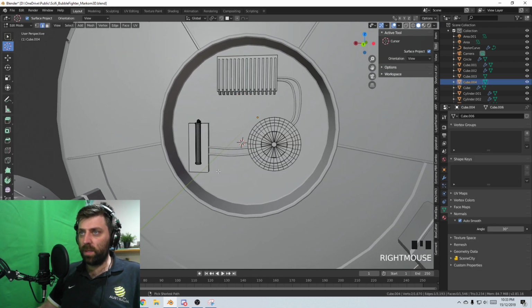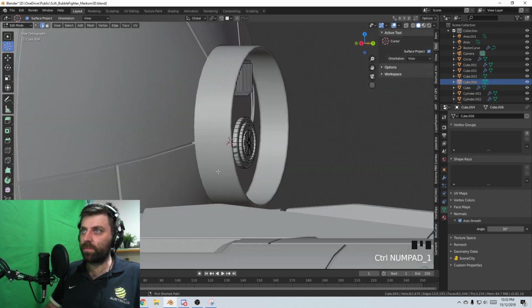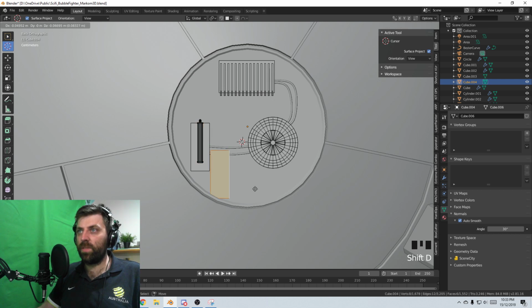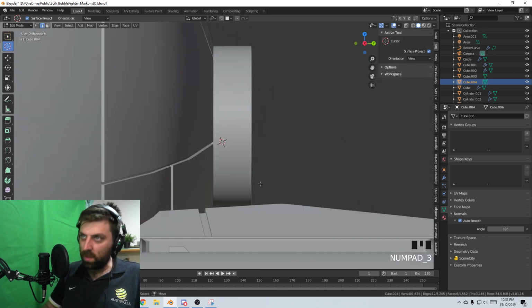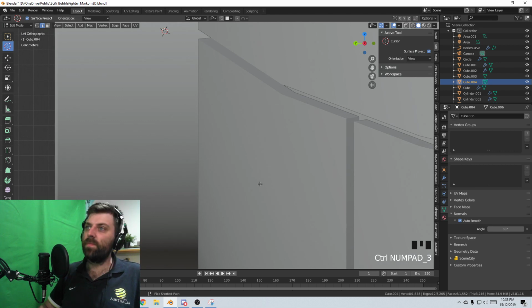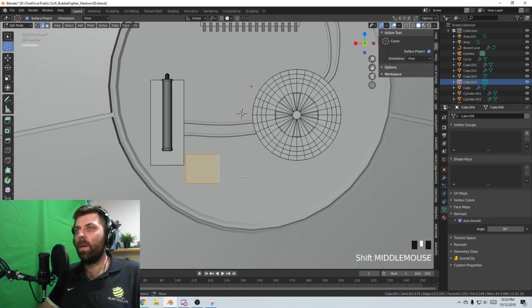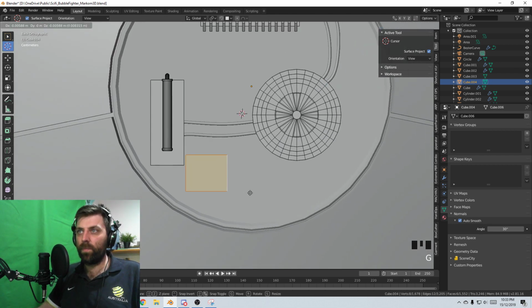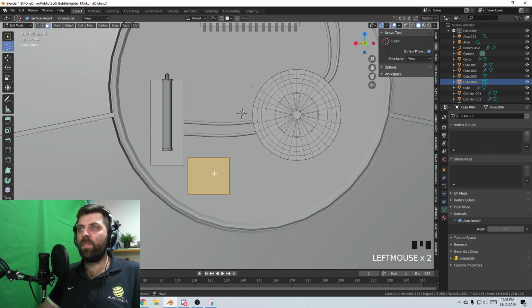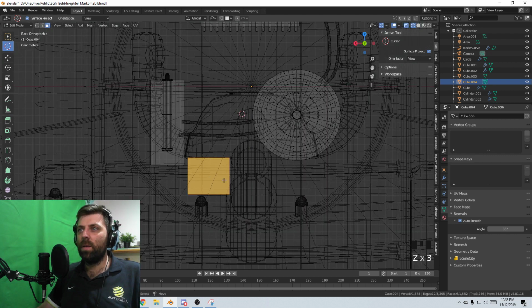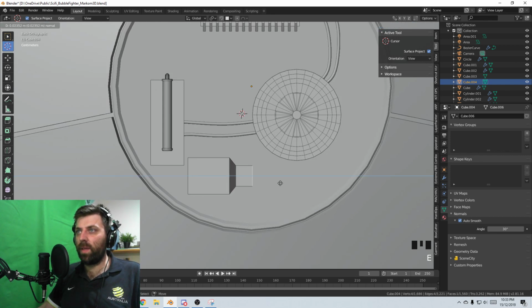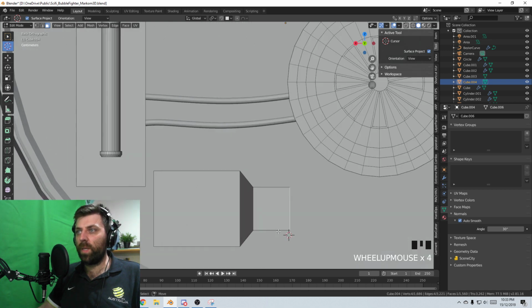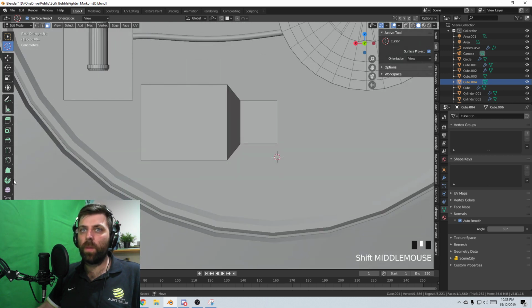Let's grab this box. Come in here, Shift D, scale on that thing. Come on. There we go. Scale. Let's grab this face in here, back to solid, E to extrude, scale that in, and then we'll throw in a spin tool while we're at it.